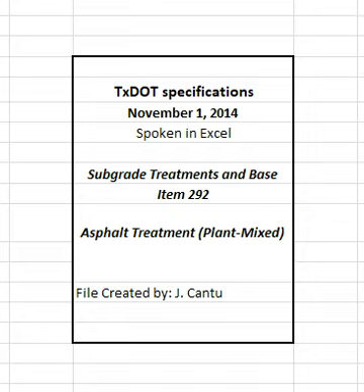4.7 Surface finish. Use surface test type A in accordance with item 585, ride quality for pavement surfaces, unless otherwise shown on the plans. 4.8 Opening to traffic. Open the completed course to traffic when permitted or directed. If the surface ravels, flushes, ruts, or deteriorates in any manner before final acceptance, correct it at the contractor's expense and to the satisfaction of the engineer.